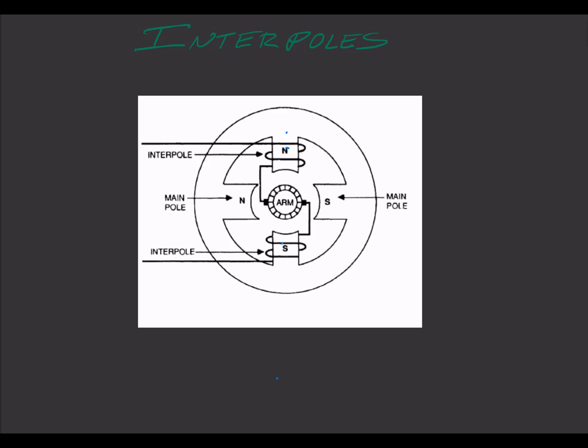And notice as the current through the armature, in other words the load, increases, the current through the armature has to increase, then this magnetism will increase, which will keep the armature reaction in check. That's the purpose of interpoles. You will find these in aircraft wiring diagrams, particularly of start generators. You'll see that there are interpoles. Larger turbine aircraft will have interpoles in their generators.